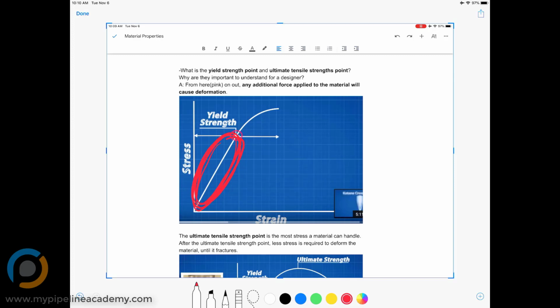Not necessarily. It tells you that it's a very stiff material. And yes, usually a very stiff material is going to be associated with a higher yield point. But a steep slope tells you that you have a very stiff material. Whereas a very gradual slope tells you what about your material? I guess the material has some give, some flexibility. Exactly. Yeah, that's right.